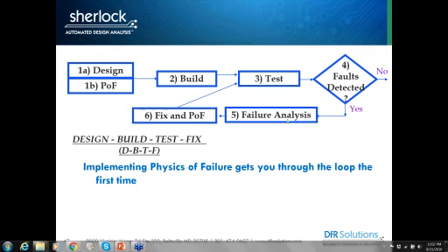It's not mature; it's very difficult to do physics of failure on that type. Now, if it is a geometry that's similar to an existing device, I would say yes, if it's just a slight variation on a BGA type of device or something like that. But if it's a totally new device with new geometries inside or some type of interconnect structure, we definitely have to go to a 3D FEA on the device and do a detailed model of it. I can get a little bit with Sherlock as far as new technology, but really we're looking at a detailed FEA study at that point.